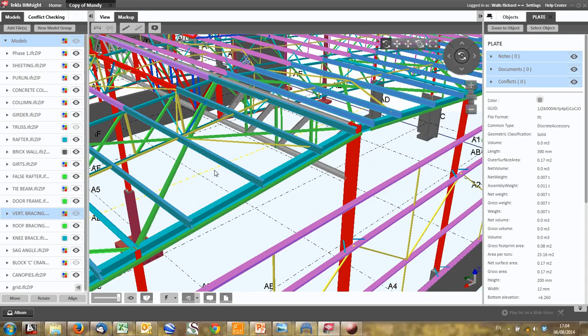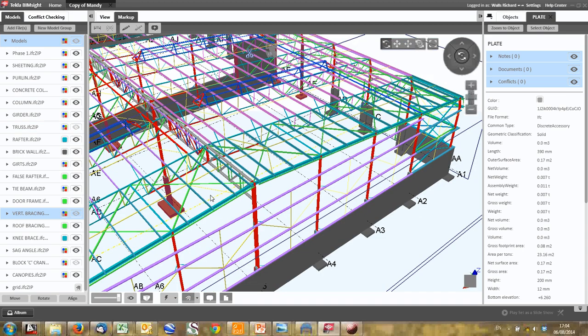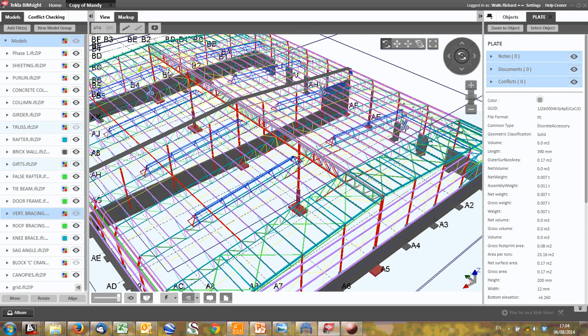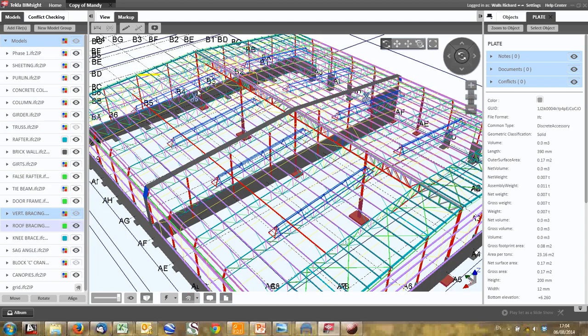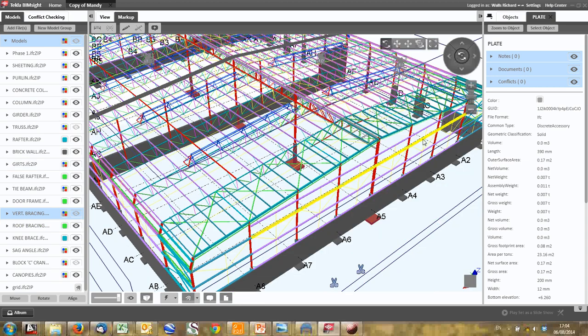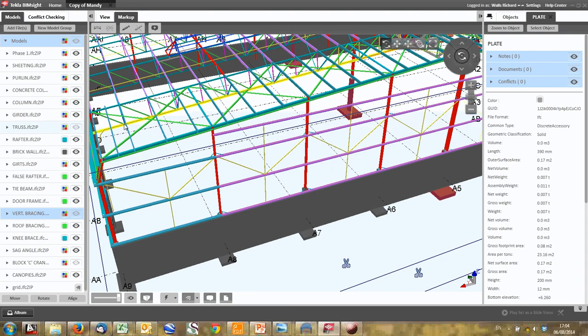If it's not there, then the bracing is not here. How do I get the load all the way from here to here? Because that's where my stiffness is, my stiff bay. I would have to put those circular hollow sections, those pipes, all the way along the building, from one side to the other, to get the load into that brace bay. That's why you need to have a brace bay to support your gable columns. And when you do your building setup, you need to make sure your bracing matches your gable columns. If you don't have that, you've got a very big problem.